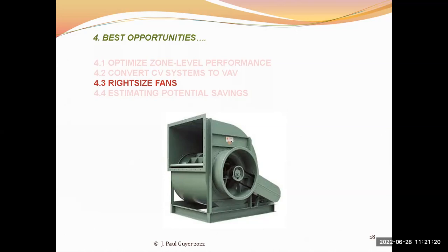And the building maintenance staff is typically going to be limited to just one method of determining the potential for right sizing of the fan, and that is measuring fan system static pressure.